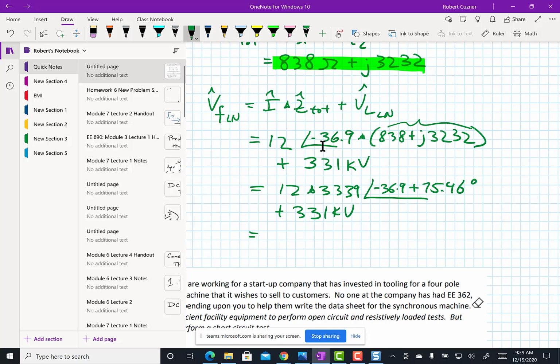Looks good. Okay, great. Now I've got a 40,000 volt drop. You say, oh my goodness, that is a lot. Well, compared to 300 kV, it's not that bad. It is bad. Remote communities suffer from this problem, but this is what's called a weak grid. So I got that voltage drop that I have to supply from the other end. And then the angle, but a lot of it's reactive, so it's not going to be as bad as it looks.